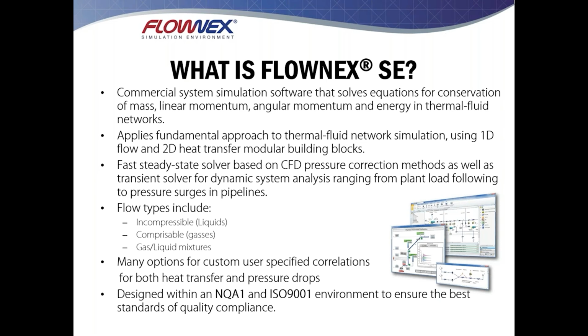Due to the nature of the solver, the networks can be very generic. There's no limitation in how the components have to be connected, and it gives you very fast solutions. Unlike CFD, where you have turbulence models to account for pressure drops, inside of Flownex we use empirical correlations on top of these conservation equations to provide values for, say, wall shear stress terms or heat transfer coefficients. All of these validated correlations are used in conjunction with the fundamental governing equations and provide a 1D model of a system or of a component.